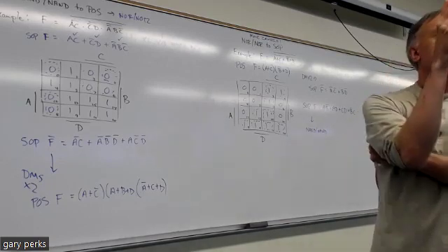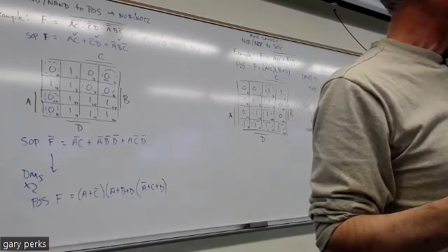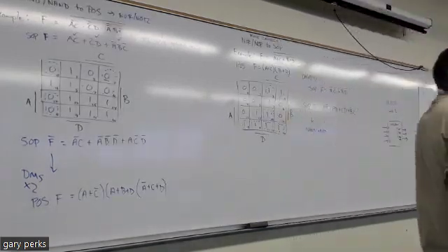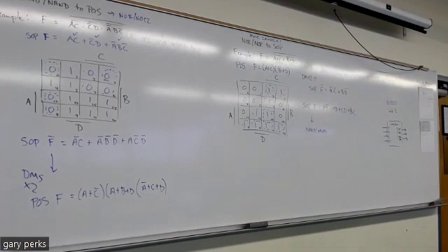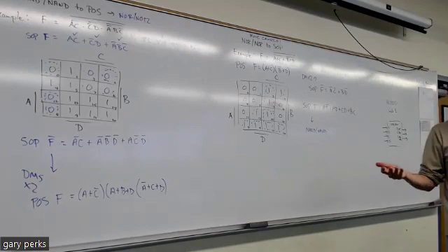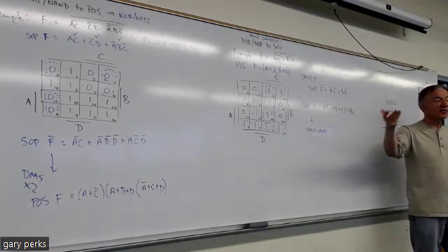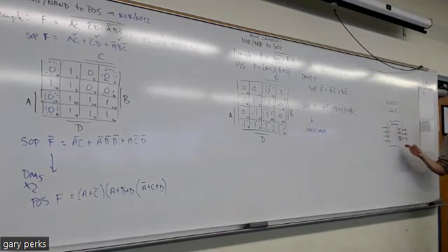Part of the lab is to compare your elaborated design that you get from your modeling to a schematic that's provided. And it should have the same number of gates. I think there's 12 gates. If your design works, like if your design for each one of these outputs gives the correct truth table, and remember, these expressions are logically equivalent, so your outputs should all be in sync.